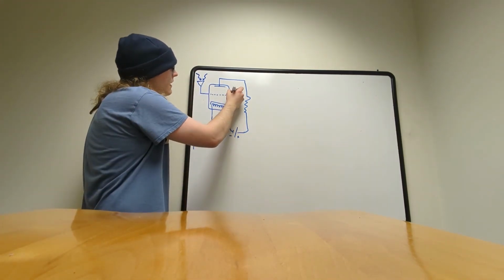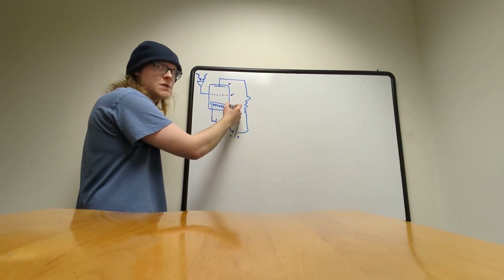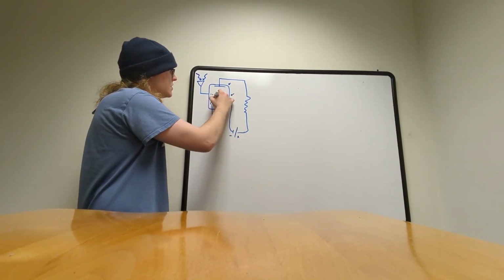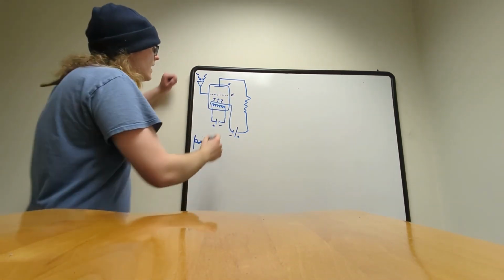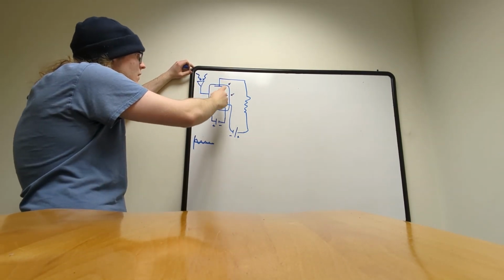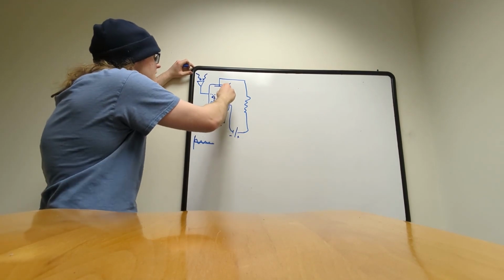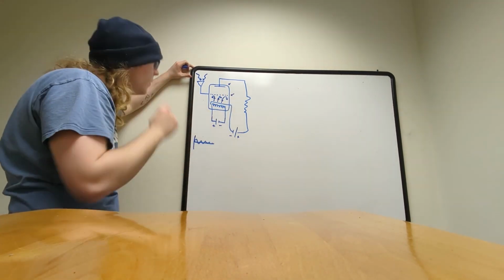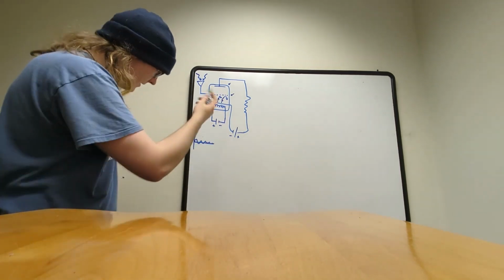So take note that the distance between this grid and this cathode is much closer to this negative side of our current, which is going to be doing the thermionic emission, emitting those electrons across that vacuum space. Now, even if the voltage across this is very small compared to maybe this voltage up here, it will have dramatic effects on the flow of electrons through the circuit due to its proximity to the cathode and those negative electron charges.